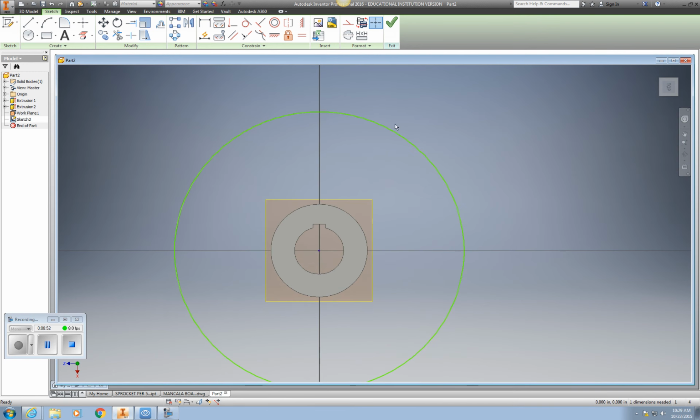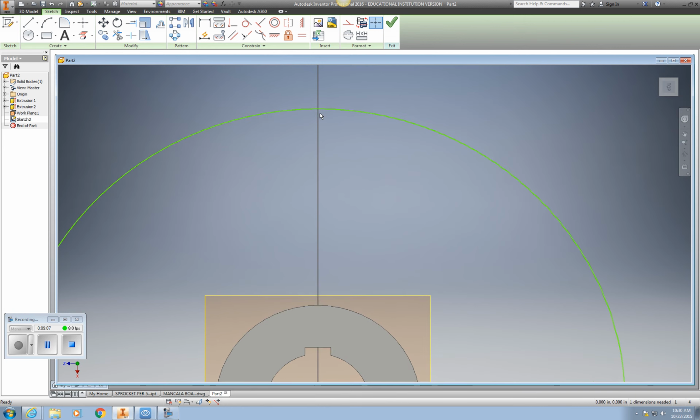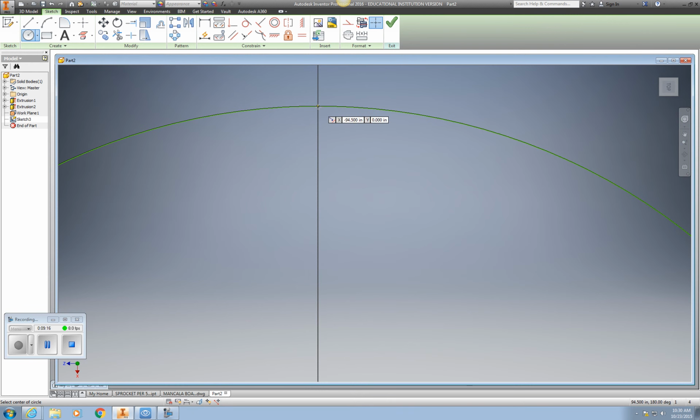And let's go ahead and look at this carefully, because it's made up of several outside notches or teeth. There's 20 to be exact, and they have a 9-inch radius and they're equally spaced. So what I would like to do at this point, I would like to go up to the top quadrant, put a circle in, and it has a radius of 9, which would be a diameter of 18.